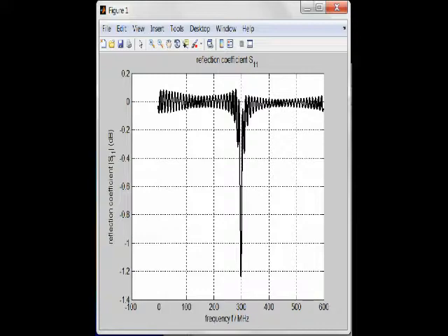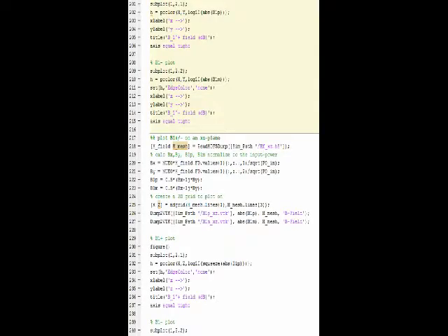as 300 megahertz. To plot the feed point admittance, we create a figure. We plot the frequency over 10 to the 6. The first one refers to the real part. The second refers to the imaginary part. And we have the plotting function. After that, we have the X label, Y label, and the legend.